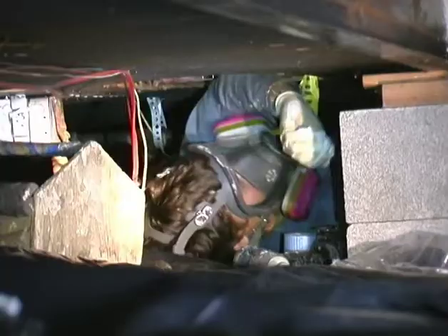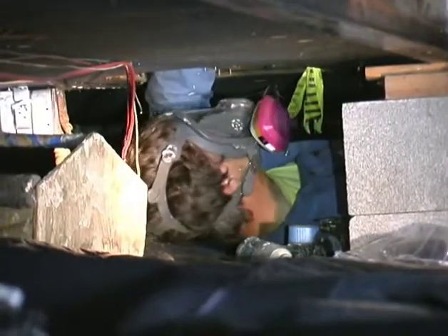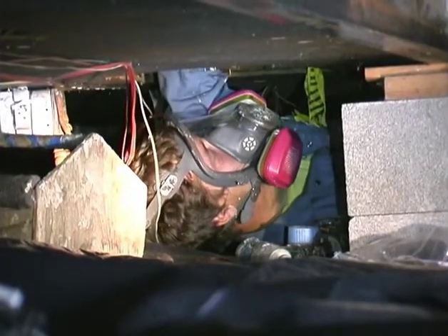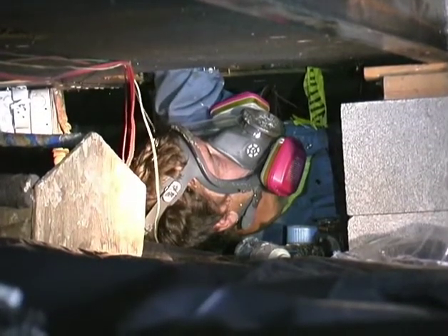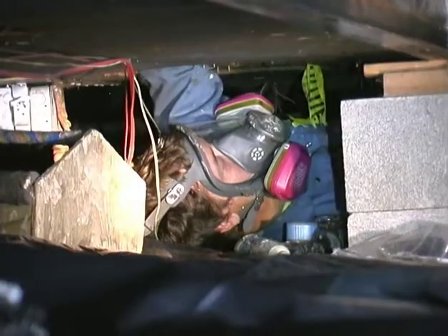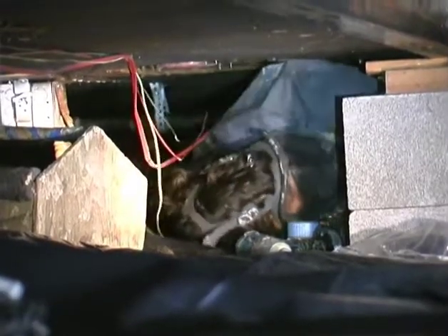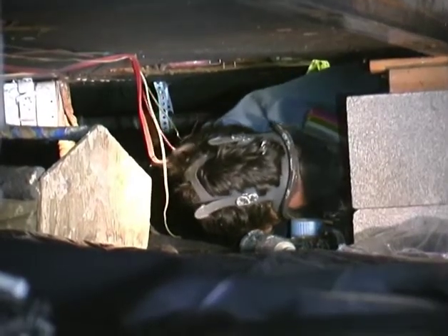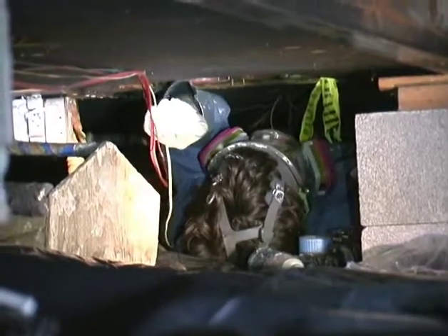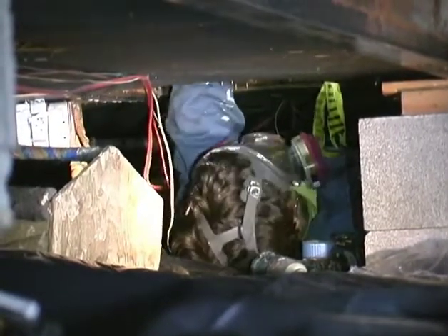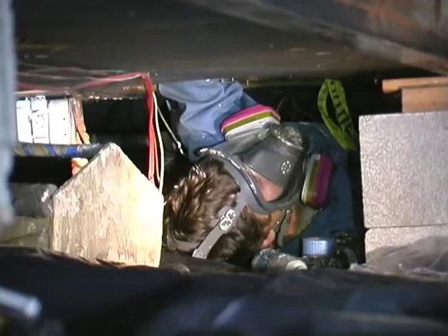Now he's using mastic and embedding that in some fiberglass tape and making a nice tight seal on that furnace to main trunk line connection. The working conditions down here are quite difficult. You can see that Jake's laying on his back. He doesn't have much room, but he's doing a good job. This is one of the most important parts of sealing a mobile home duct system. The number 1 place to seal is the furnace to trunk line connection.